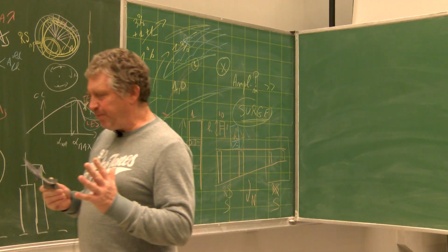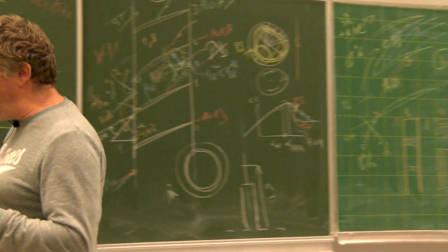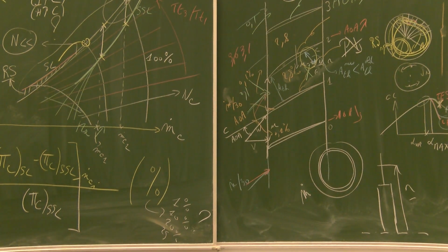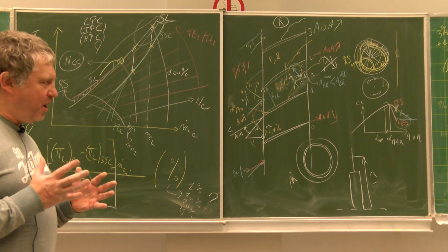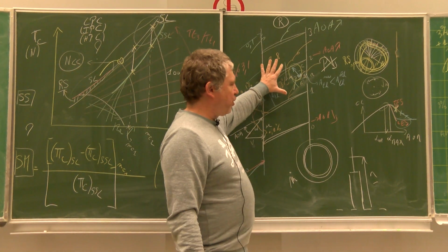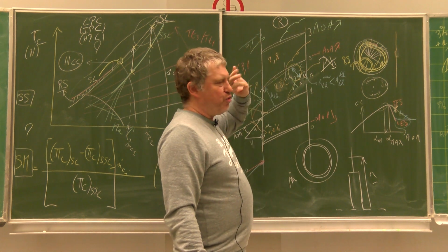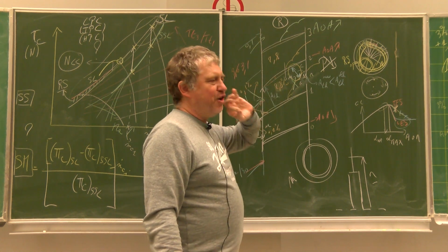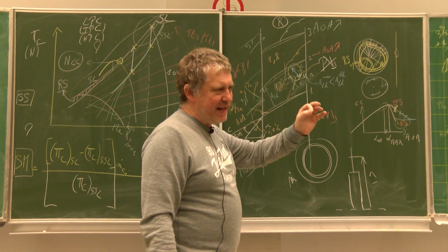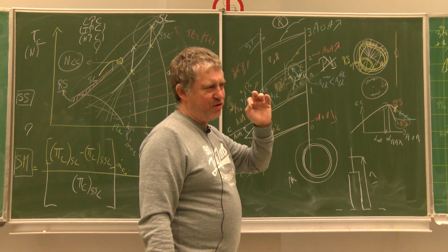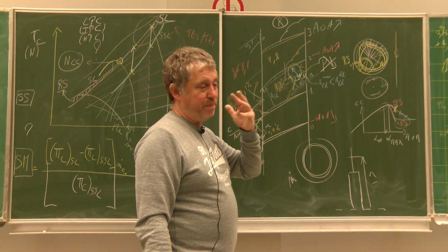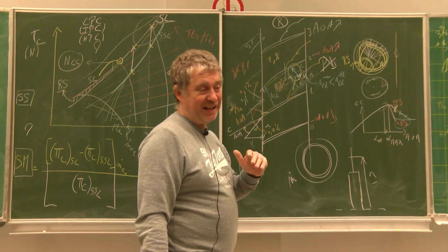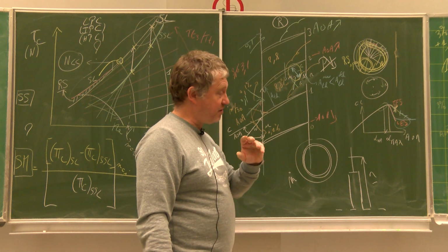But you see that these two phenomena, rotating stall and surge, are quite similar. One, rotating stall, is related to a small part of the blade, small m dot, not leading to very high consequences, almost no consequence, I would say, at the level of the performance of the compressor, but mechanically it can be dangerous.